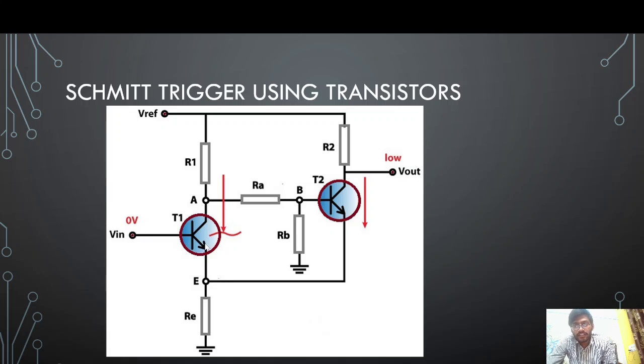then the transistor T1 will not conduct, whereas T2 will conduct due to the V reference with a voltage of 0.98. At node B, the circuit will be treated as a voltage divider to calculate the voltages at VA and VB. Therefore, when we increase the input voltage Vin, the transistor T1 will start to conduct.